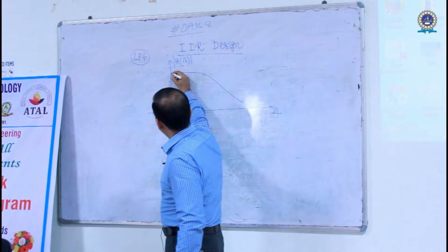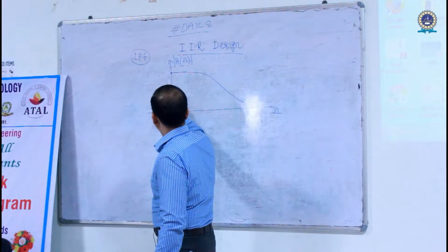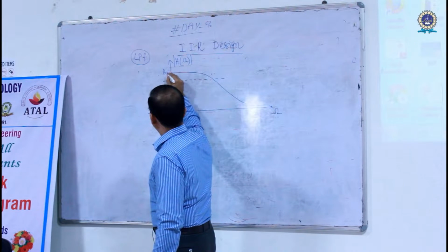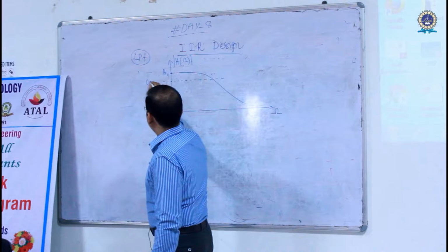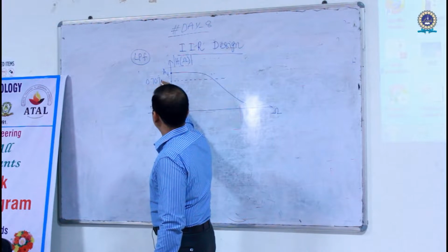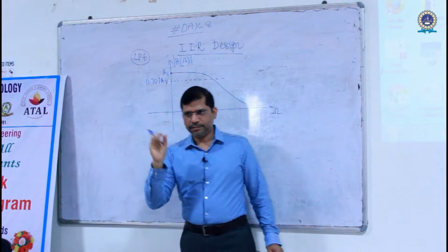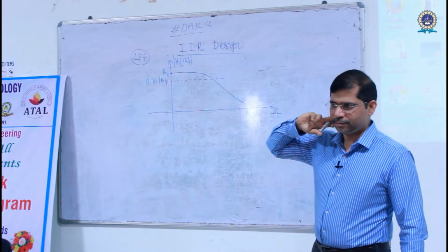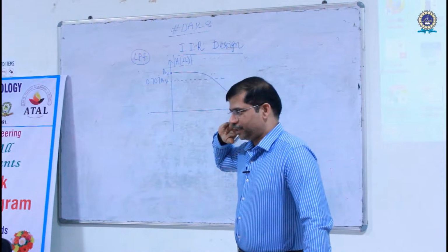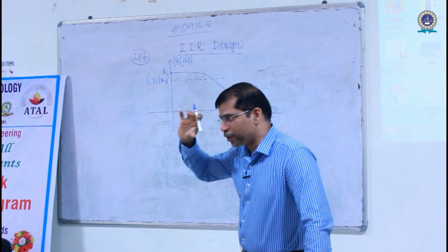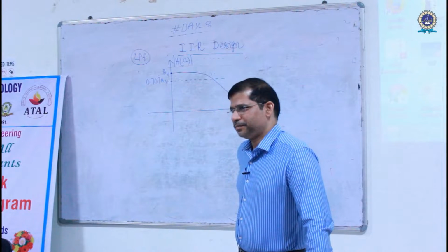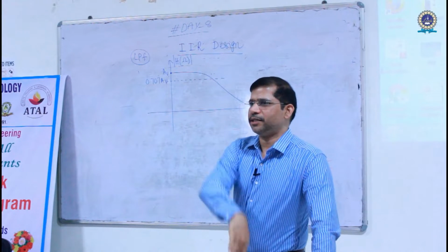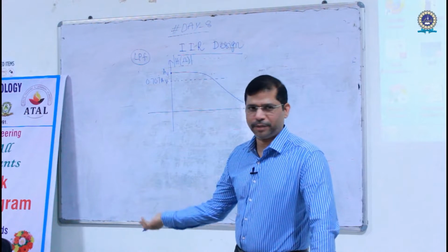Let's say this is the maximum magnitude. Normally we draw a line here, and let us say this is A, or AV or AI, whatever it is, and you call this 0.707 AV, very standard numbers, right? Why is that? Why is it 0.707? Why 1 by root 2? If you understand 3 dB, you will automatically understand, because log of 1 by root 2 is nothing but -3.